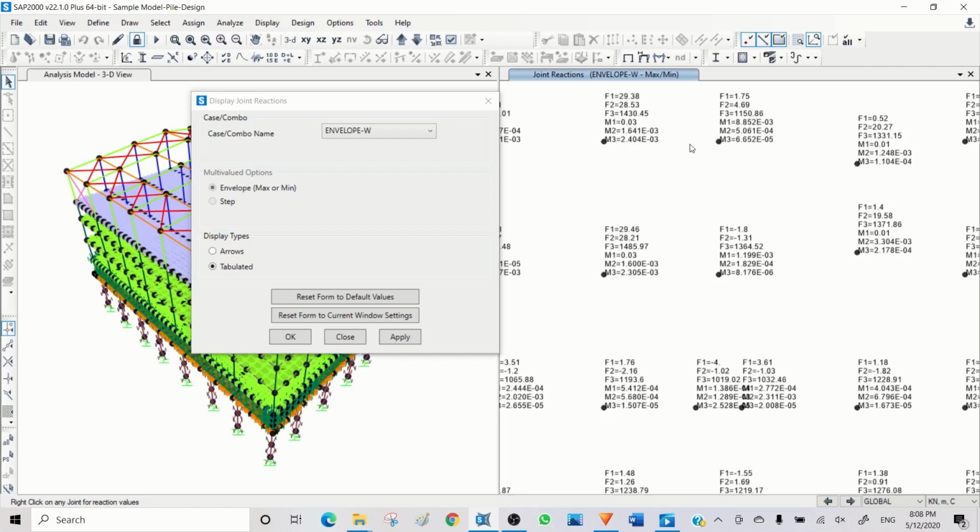We just need to bear in mind that the space between the piles shouldn't be less than 3 times the diameter of the pile. Otherwise, the areas under pressure, those bulbs, interact with each other, and that will decrease the end bearing capacity of the pile. So they should be reasonably far from each other, and the recommended distance is 3 times the diameter of the pile. So for a 600 pile, it is a minimum of 1.8 meters center to center.